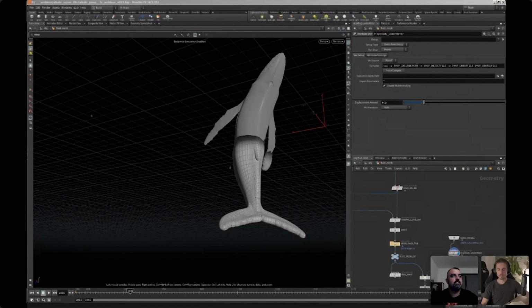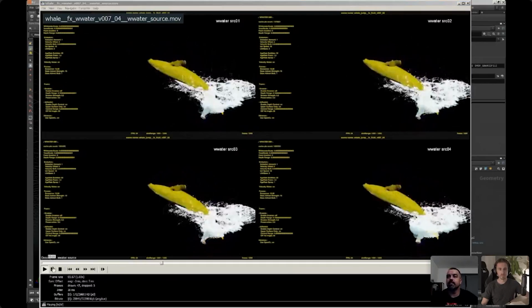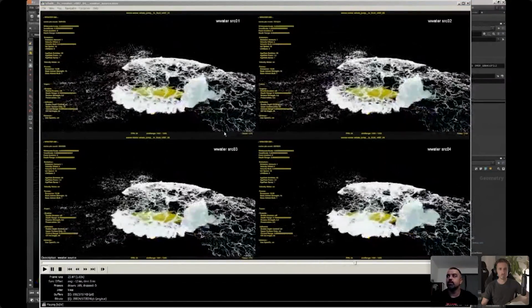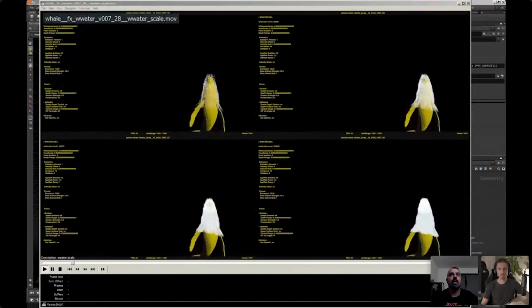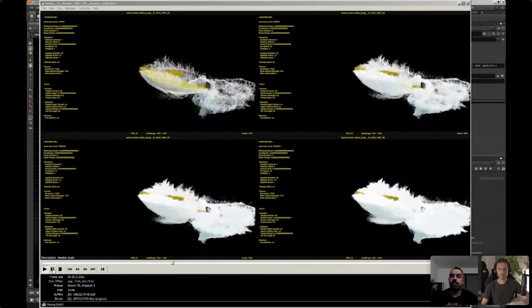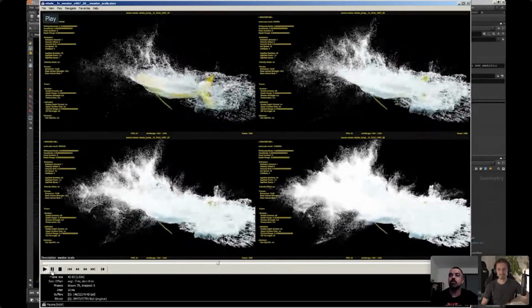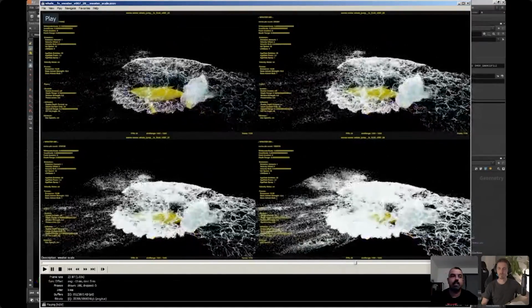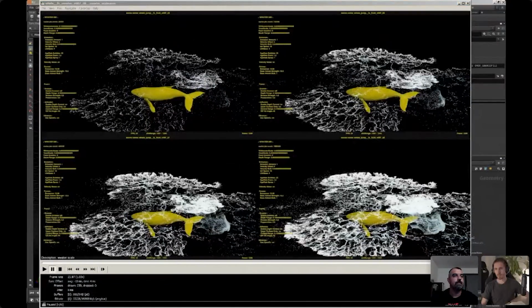After that, everything is again based on the whitewater sim. Again, doing the wedges, playing with the settings, trying to learn from them. Like I said, we share all our wedges with the workshop. There are more than 300 wedges just for the whale jump, and there are also some for the beach and rock splash. So you don't need to do all of them, but it's a lot easier to learn and understand how they work, and how to get foam patterns from the new whitewater solver.